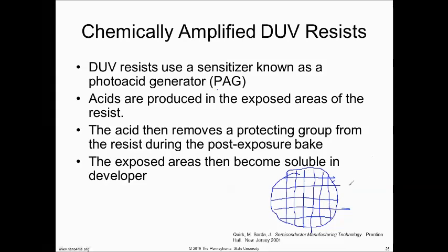That's even worse. So anyhow, this is my round wafer, and each one of these squares, I'm going to say, is a microprocessor, like a Pentium chip. Does everybody see that? On each square, I'm going to have literally billions of transistors. And if I try to put my mask on here and align to this die and perfectly do an overlay, so that these things that are as big as a virus get matched up, so that I do one layer on top of another.